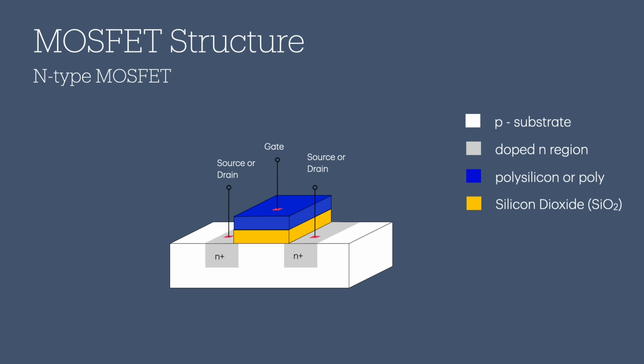Next, the silicon dioxide, also known as SiO2, plays a crucial role in the functionality of the device. Colored orange in the slide, it serves to insulate the gate from the substrate. The key operations of the device take place in the substrate region beneath the gate oxide. It is important to note that the device is symmetric in terms of the source and drain components. Lastly, the vias. This is a metal with high conductivity to provide low resistance connections.